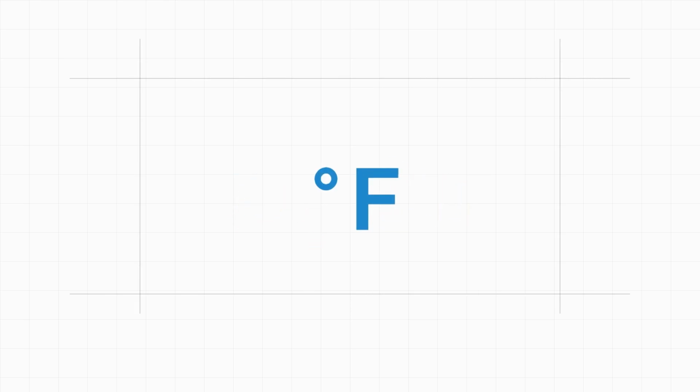You plug in four things: your surface area in square inches, the surface temperature, the ambient temperature, and the emissivity of your material. It handles all the unit conversions behind the scenes and gives you results in both watts and BTU per hour. Now here's why the formula matters.